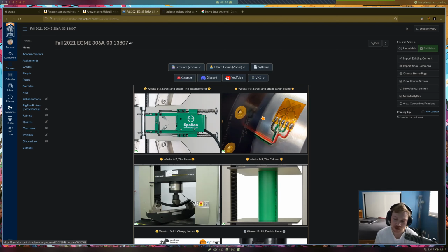Both of them might be very accurate, and it's not going to be substantial whether the extensometer or the strain gauge is more accurate. They can both be within an acceptable tolerance. If that's the case, then in our memo we're going to talk about which one is more useful in practice. The extensometer might be a little harder to set up because you have to line up those blades on the rod.